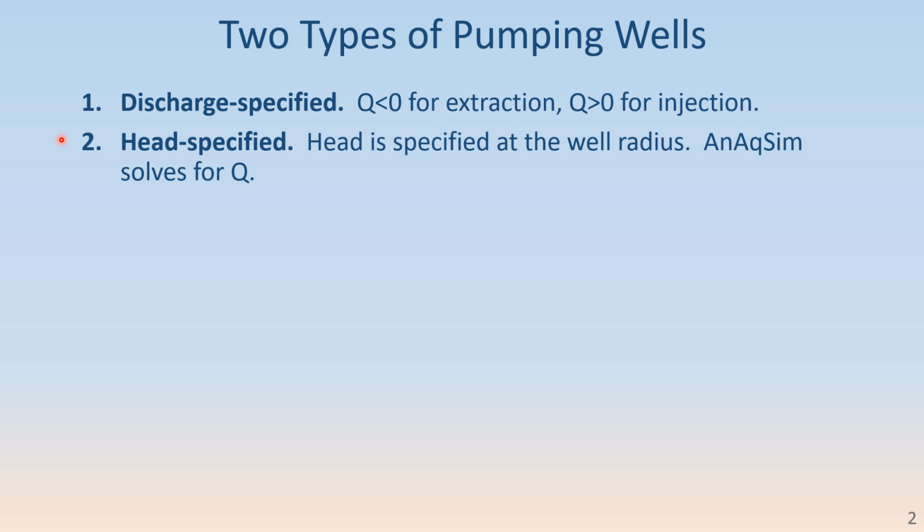And the analytic element method is excellent at representing pumping wells, much better than numerical methods like finite differences or finite elements, because the analytic solution has the proper logarithmic shape to the drawdown curve, which numerical methods generally lack. They are assuming linear variation or something like that.